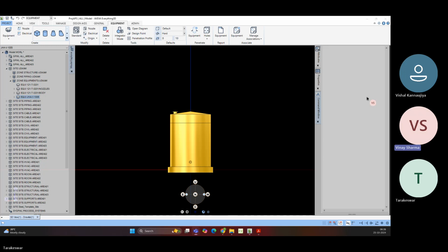Flow will happen in a normal pipe also, but why do we need free draining? For example, some liquids, if we go for a sulfur recovery unit or a flare unit, in that case it's not easy for a straight pipe to go. There should be some slope. Slope means deflection in the pipe, simply put. Why we require it: so that free drain would be there.